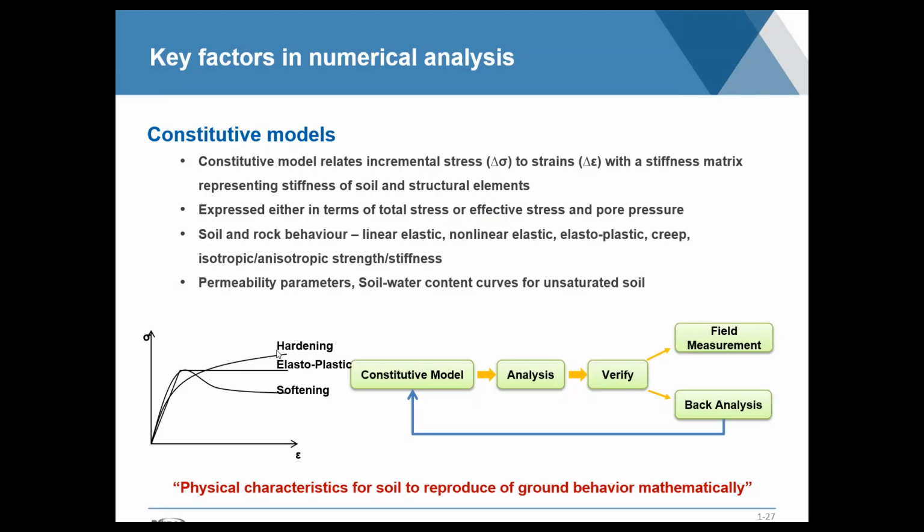Before we get into meshing, I'd like to cover a little bit about the theory behind how the materials are captured in finite elements, and that has to do with these numerical theories, constitutive models. They basically relate the relationship between stress and strain. While the linear part, of course, is going to be similar for all of these different models, what we really start to see differential between all of them is the nonlinear behavior. For some soil conditions, there might be hardening as you increase the stress. For some of them, there might be softening. So it all depends what your local condition is and what it is you're trying to capture.